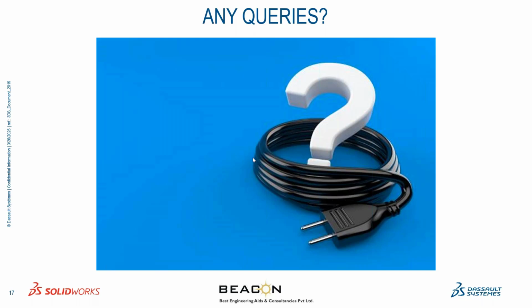And here, Mr. Daniel Prabhu is asking if it is possible to import schematics created by other software. So we can import DWG, DXF formats into the software. And if we have any kind of circuitry there, what happens is when you're bringing it in from another software, it is basically lines. It is not wires. Here under SolidWorks Electrical, it is wires. So wires is where we will be able to give the data. So some sort of reworking must be done to make sure that it is compatible with our software. But that is about it. And you have asked about the file extension. I have mentioned that it is DWG or DXF formats.